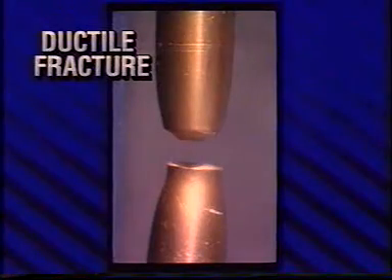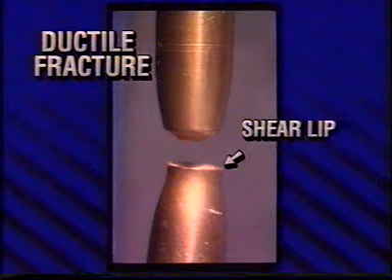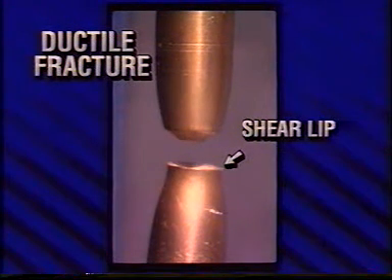The process is known as microvoid coalescence. The joining cavities progress outward in a generally transverse direction. Before the fracture reaches the surface, however, it suddenly changes direction from transverse to a slant of about 45 degrees. This slant portion of the fracture is the familiar shear lip that forms the dull and fibrous appearing cup and cone fracture typical of tensile fractures in ductile metals.